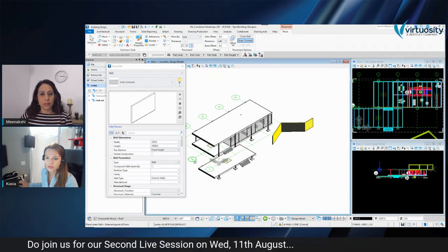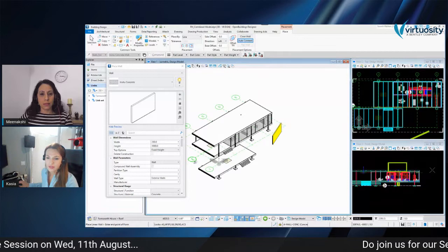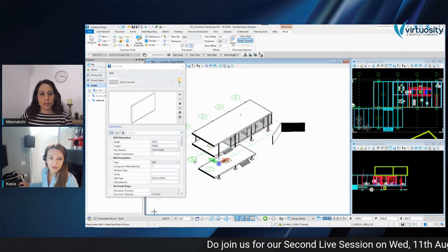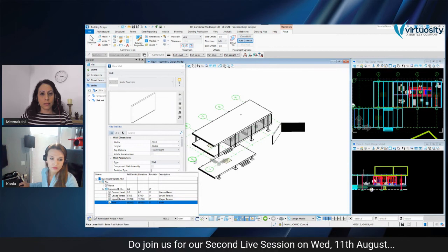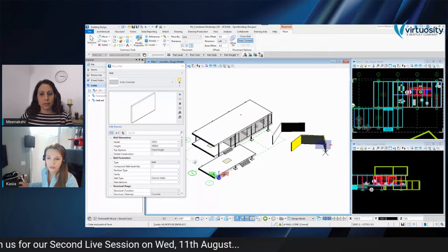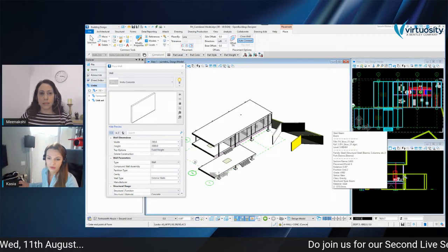It will be easier to see in the front view. It got placed exactly in this active plane. And if I change it to the ground level, for example, again, I just draw anywhere in the building and it snaps to that active plane at the ground level.